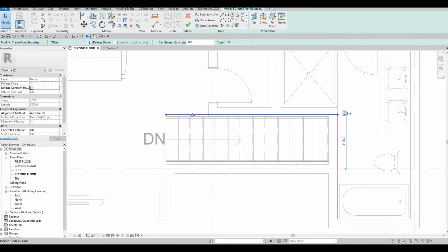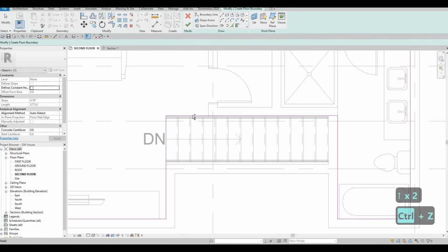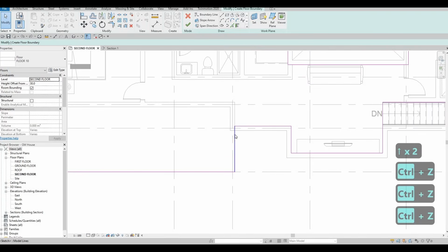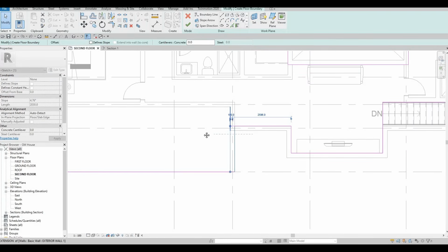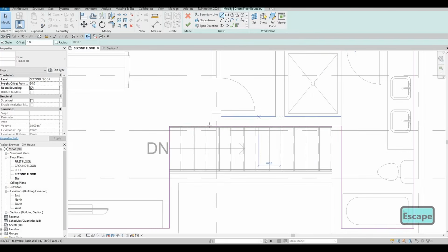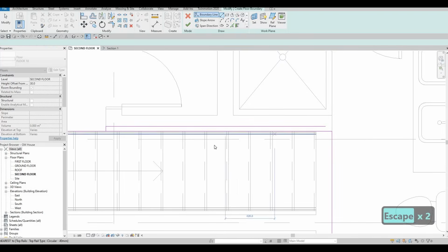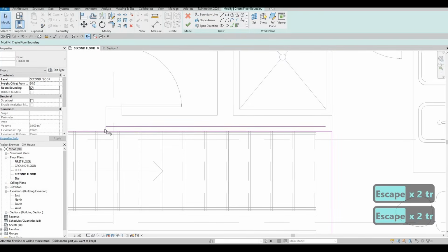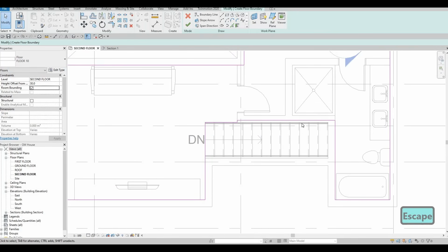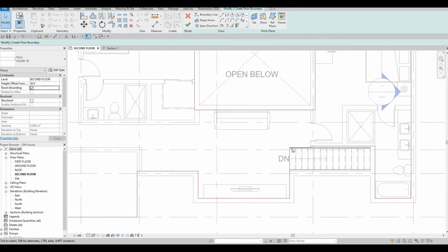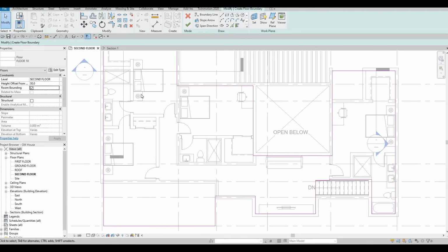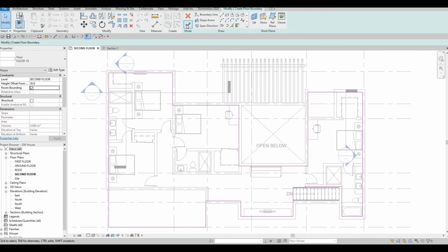And then this part, we don't need to show this part right here. I'm going to move this one a little bit as well, because it will be shown on the edge of this. So once I have it there, I'll flip it a little bit at the top. I've been sending stuff to Twinmotion all the time. That's why I know that anything that is overlapping will flicker, and that's why there's flickering in Twinmotion. It's because of this overlapping stuff.